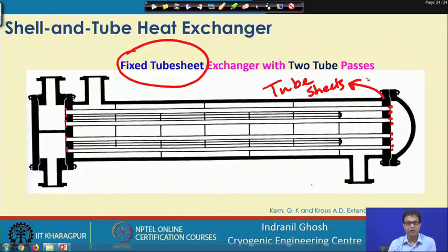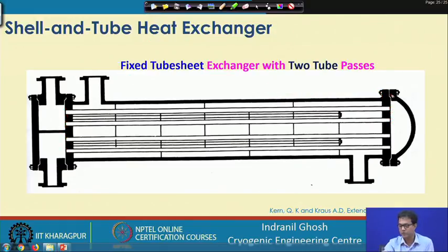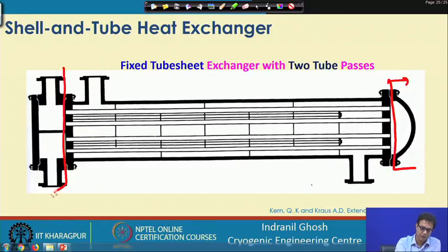It obviously gives an advantage in the sense that whenever we remove these two ends, if we unbolt this part, you can understand that the tubes are now exposed, and if any scaling has formed inside the tubes, we would be able to physically clean them.